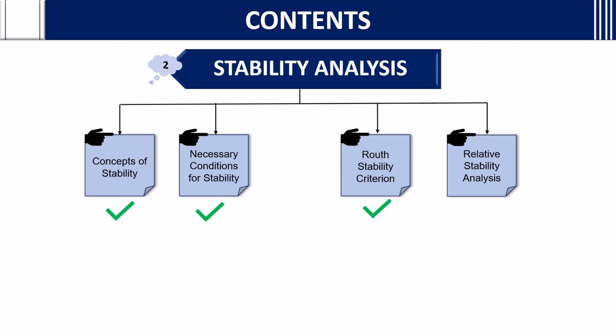So in this video, what I have done is the Routh stability criterion, and many problems have been solved. There are many more problems you can find using some sources. Then you can solve them, so that all the sums are similar. What you should do: Routh stability means they will give a characteristic equation. If one row is entirely 0, then you will take the derivative and find the auxiliary equation. If it is not like that, and only the first element is 0 and other rows have some values, then what you should do